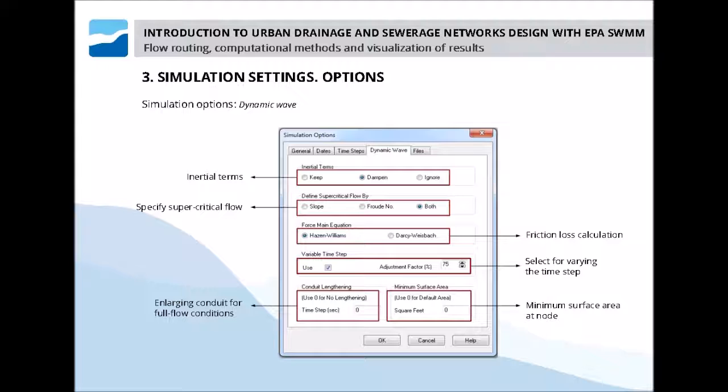All these options obviously require full knowledge of continuity equations and all of Saint Venant's equations. Only then can we operate in this user interface and personalize the dynamic wave routing model to obtain as stable as possible results with as long as possible routing periods.